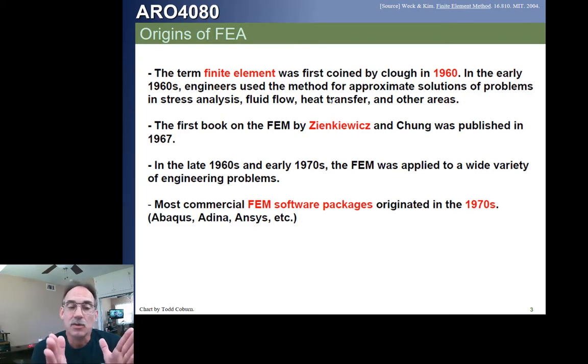But then what we found was by accounting for our displacements, we could solve the structure. And we saw other examples of that where whenever we had too many unknowns to solve using statics alone, we would try and account for the displacements, and usually the math got complicated rather quickly. Not that the math was so difficult, but solving some of the simultaneous equations was. Finite elements handles all that for us.